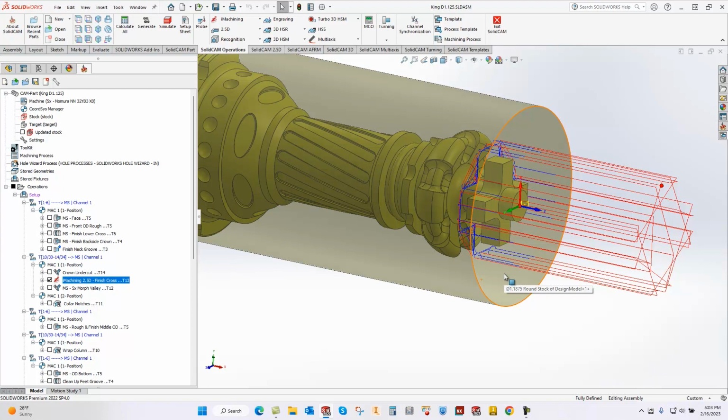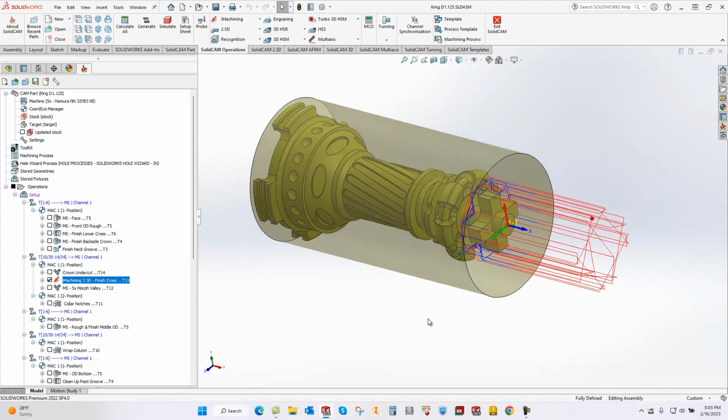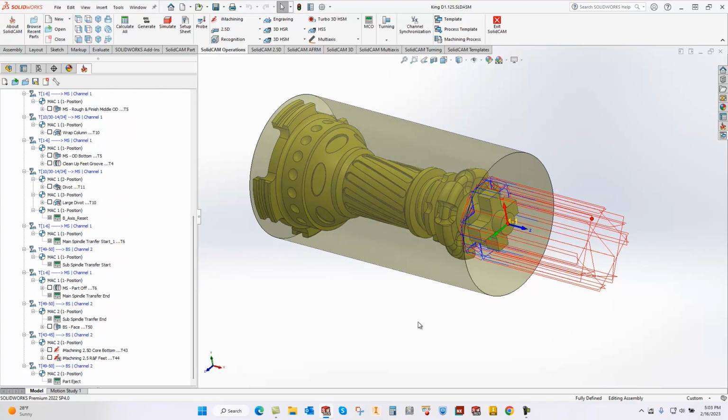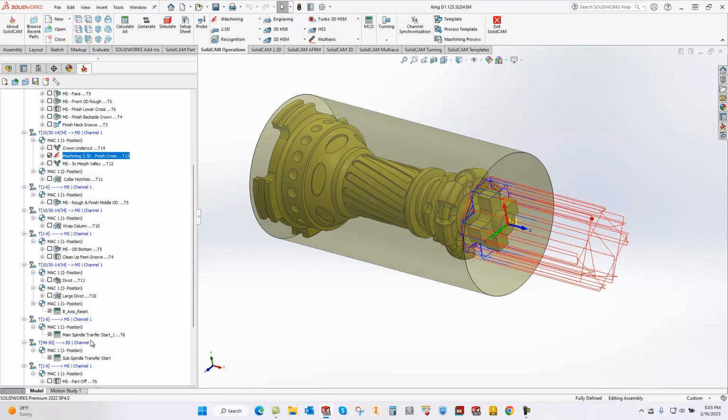Now, if this were anything harder, like titanium or any kind of steel, I'd still want to use iMachining even on a small cut like this. So it's a huge deal, and I'd love to give you a more detailed look at this. If you want to get into a demonstration, we can check out your parts, and I can get more into how well this works in a lot of different environments. You can use iMachining in 2, 3, 4, 5-axis, mill turn and Swiss, even turning. As you can see, I have a few more down here as well.